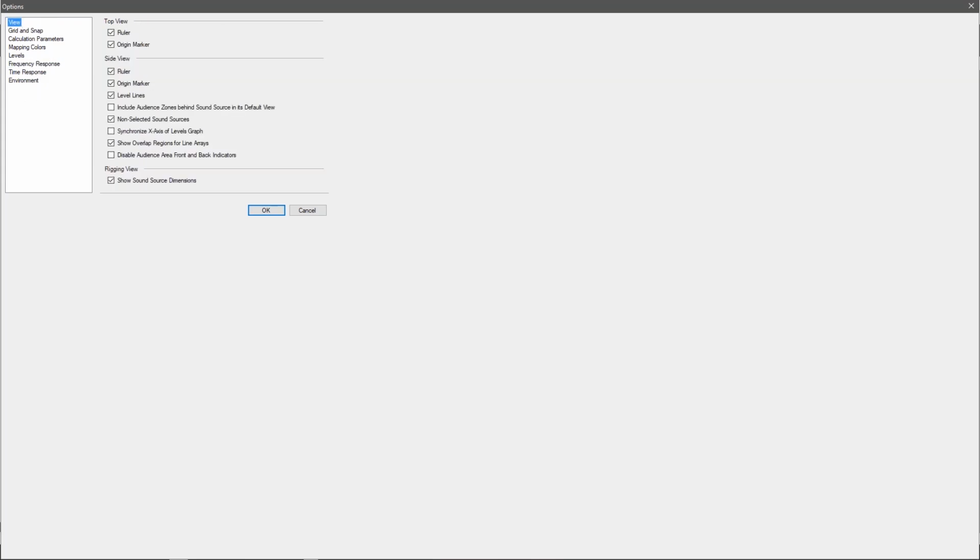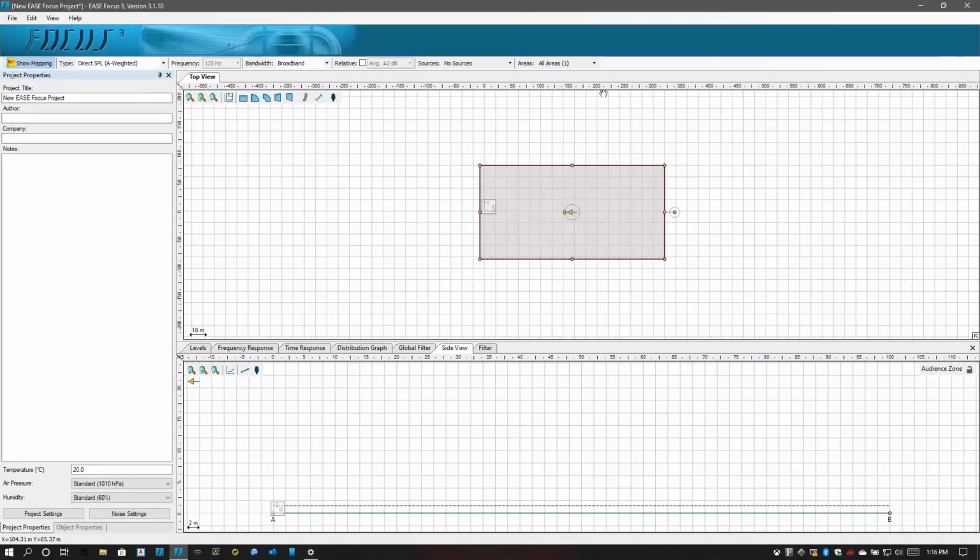First we'll go to View, and under View, we'll be able to add a couple of rulers. Under Ruler, normally it comes out like this, top view, meaning the rulers are empty. Let's go ahead and turn on the ruler. That way, while we are working, we can see what our actual dimensions are: our 0 point, what 300 meters is on our XY path, and also on our Z.